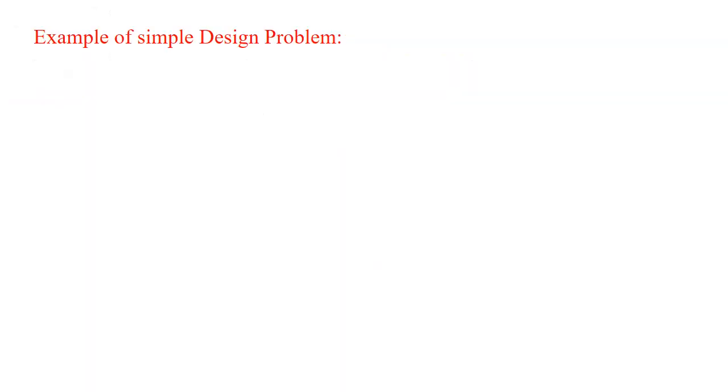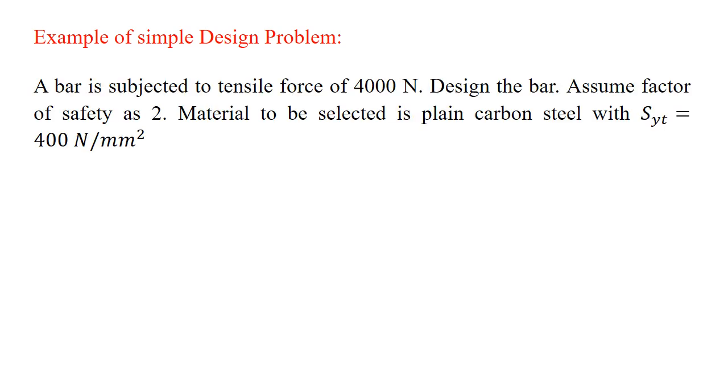If I think of a simple design problem, for example this way: a bar is subjected to a tensile force of 4000 Newton, design the bar. Assume factor of safety as 2. Material to be selected is plain carbon steel with SYT equal to 400 Newton per mm square. If you want to solve this simple numerical, what will you think?